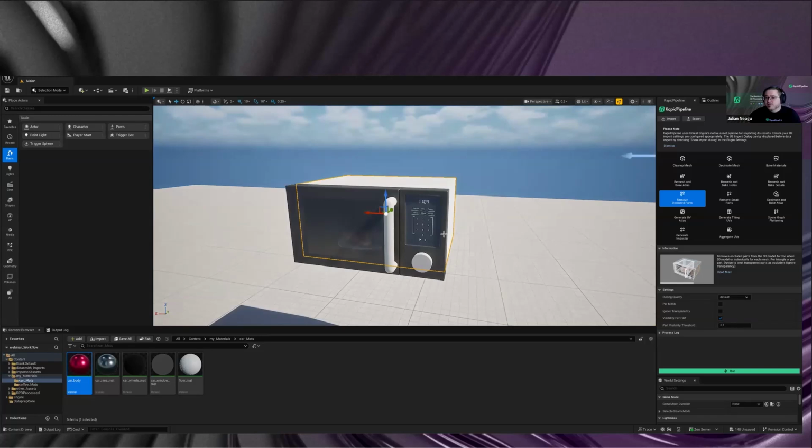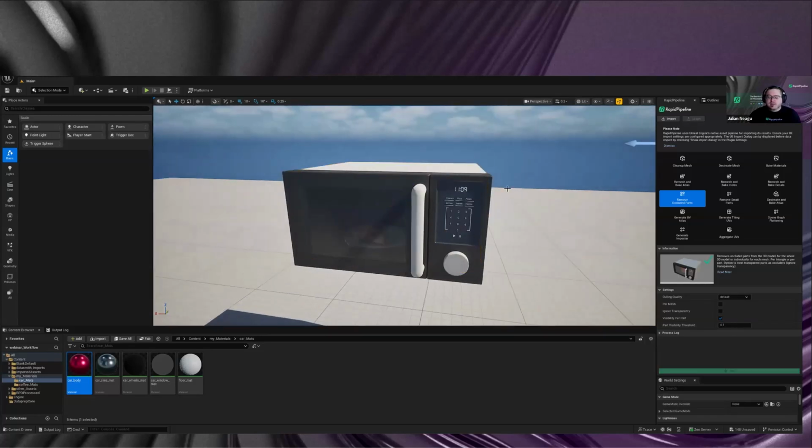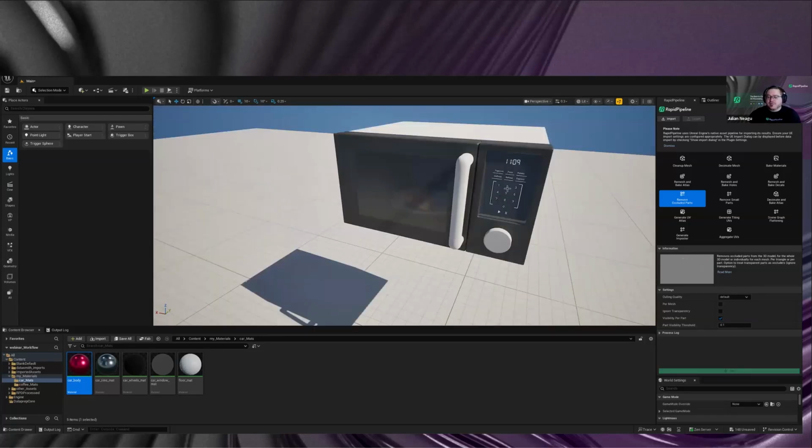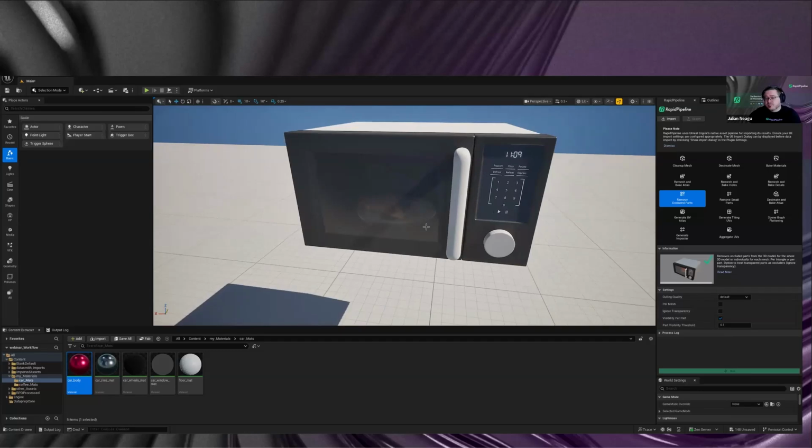So basically that helps a lot if you already have an authored workflow. You already did your material assembly, perhaps in Unreal, and then you're running a culling process. But it also could be in reverse, and we even can turn this off. We can check the ignore transparency, for example, and say, hey, we actually want to remove that interior part behind there, because maybe later in the authoring process or in a certain material variant, we don't have glass here anymore, et cetera. So that works actually quite well.